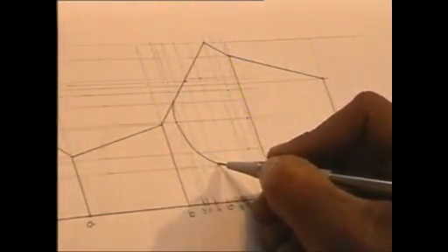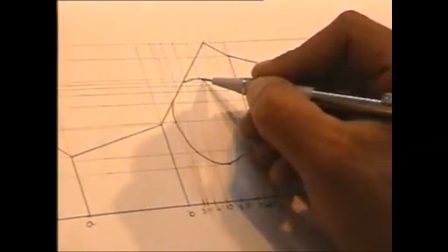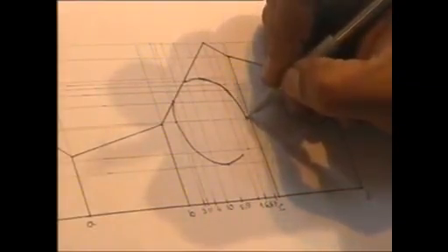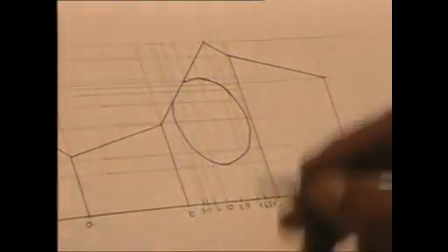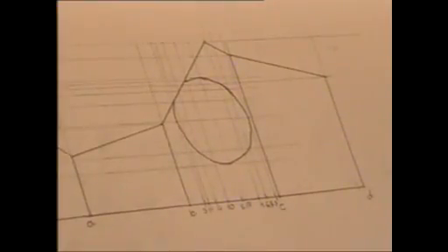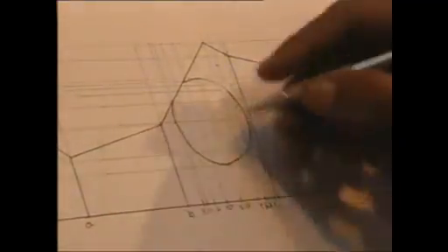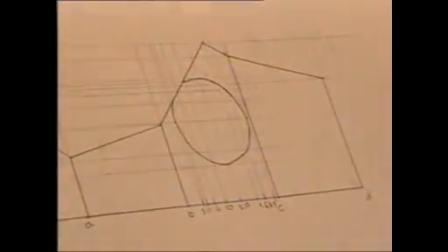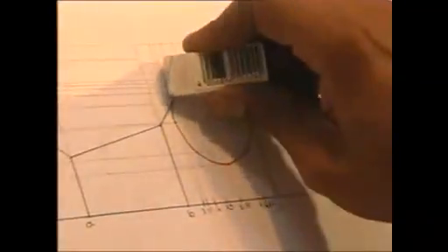And these two curves are not symmetric curves as such, though both of them are bound to be ellipses. These are ellipses actually, but the planes which form them are not making the same or equal angle, and hence they will not be identical in shape. And so the portion of the cutting plane between these two should be removed actually. That of course we can do afterwards only.